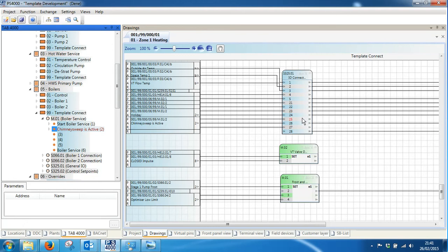There's also a heat demand output, should this literally be a zone valve, which is looking for opening a valve on an on-off basis when the system is on during the day, and it will close when it's off during the night unless it's a frost condition. This could also be used to request an external heat source, such as some kind of external request, maybe into a third-party control system, which was just an on-off request.